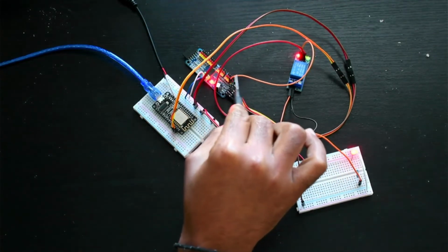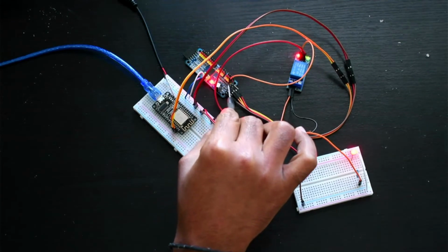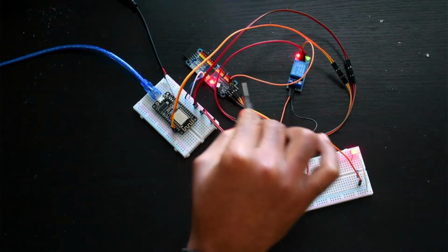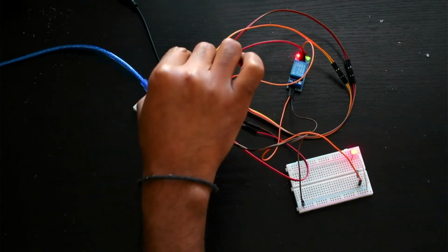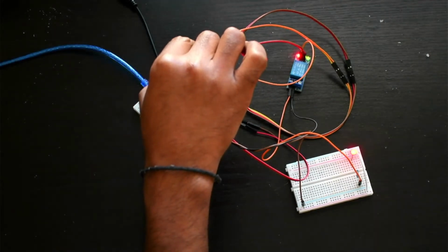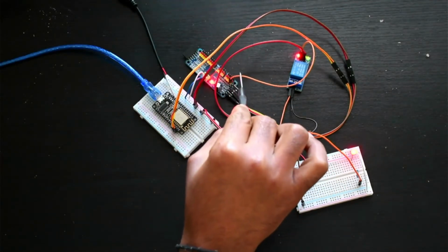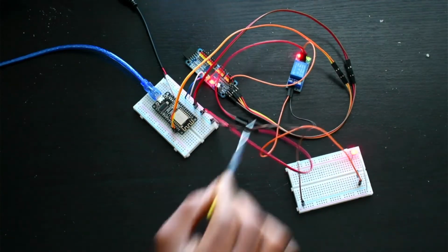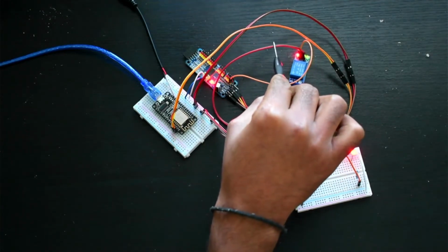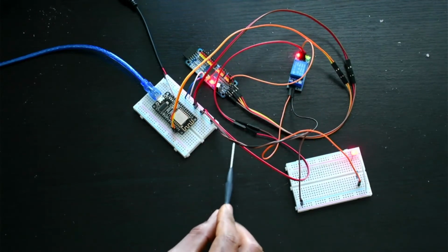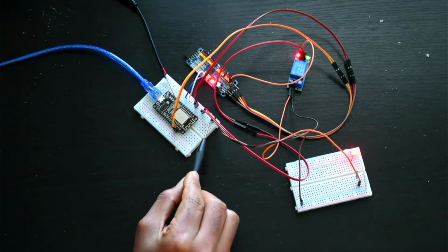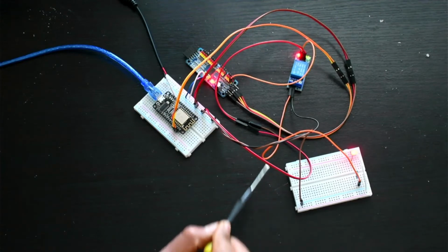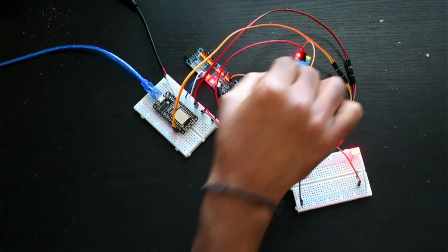This orange wire is mounted on the yellow part of the first pin because it has 3 parts: PWM pin, power as well as ground. So from the PWM pin, from pin number 0, we are going to the relay switch, and this red and brown is taking 5-volt power supply from the same breadboard from here. So this is going like this, and going to the relay switch.